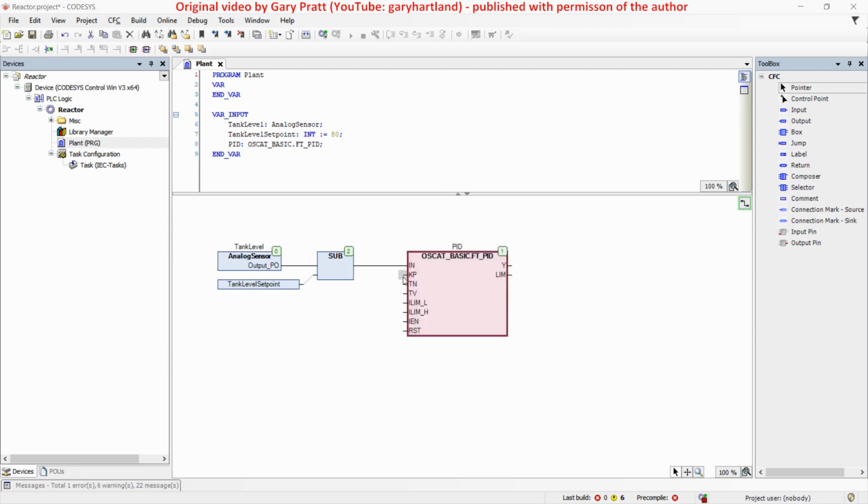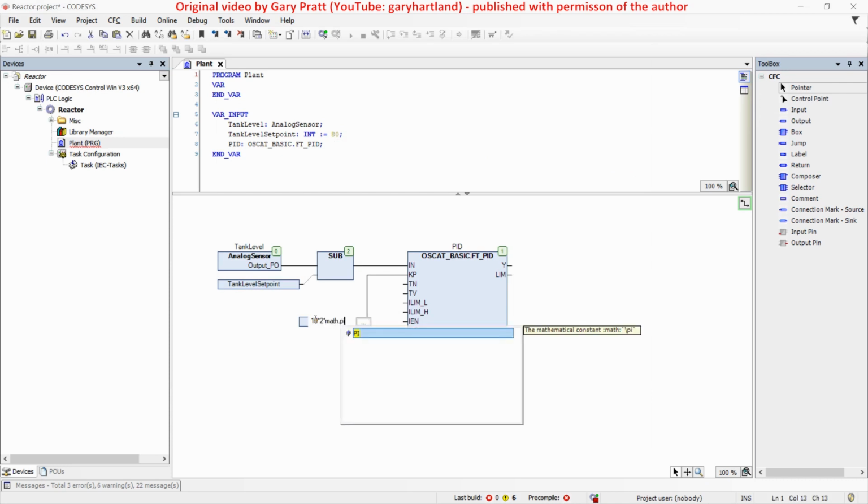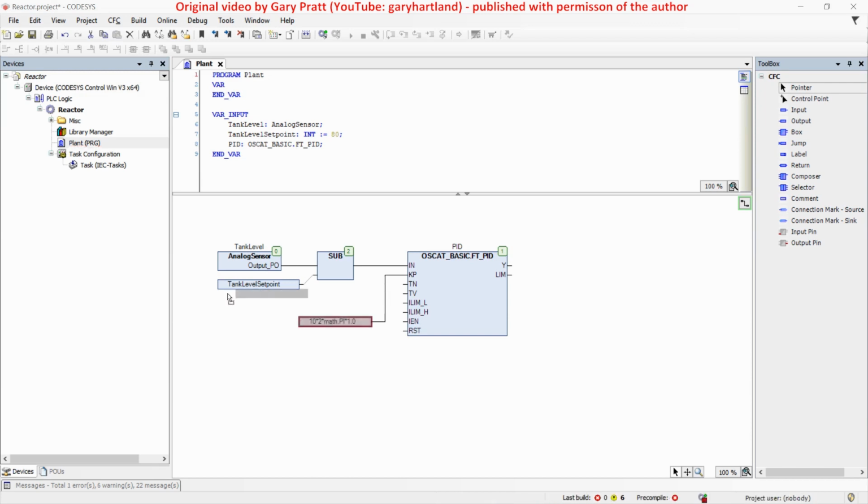For the purposes of this demo, we will use a tank that takes 10 seconds to fill at full flow rate. Since the tank is a pure integrator, it represents a pole at 0 Hz and will have a gain of 1 over 2 pi f. For a 1 Hz control loop, we will want a proportional gain to be the inverse of the tank. That would be 10 times 2 pi times 1 Hz. For now, we'll leave the integral and the derivative disabled.